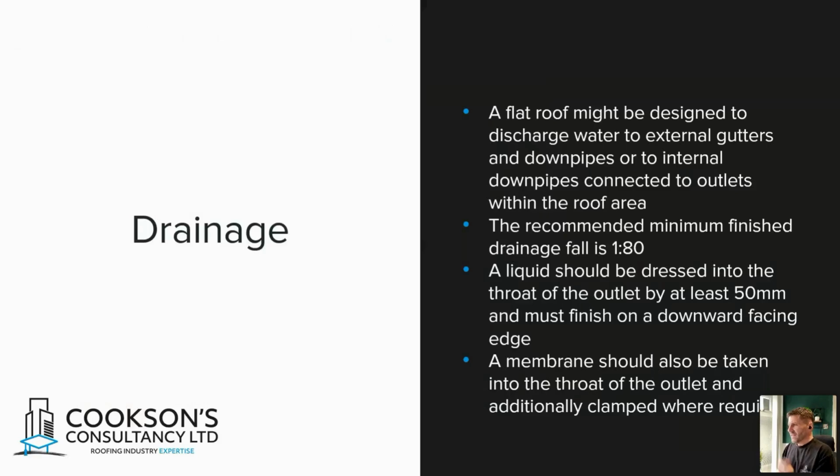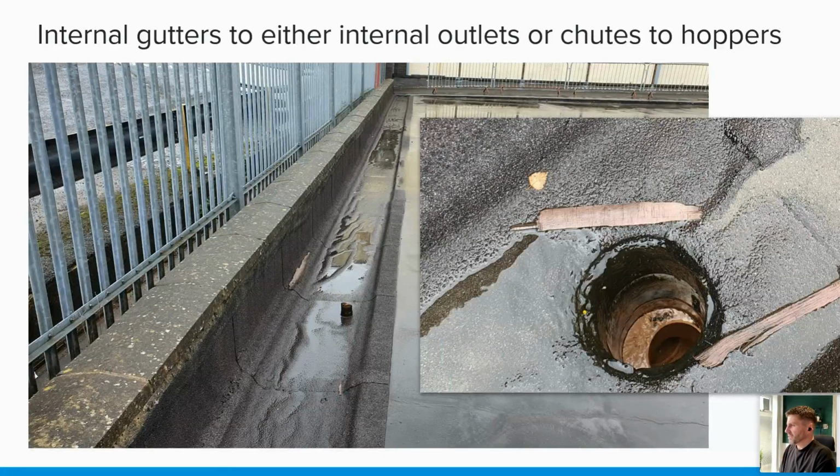So in this instance, we've not clamped the waterproofing or anything like that. So this felt has been bonded over the top and then has just been cut around here. This is a common failure point around outlets. In the previous sessions, we showed that waterproofing notoriously comes away at these details. So water can track underneath the waterproofing and down the outside of the downpipe.